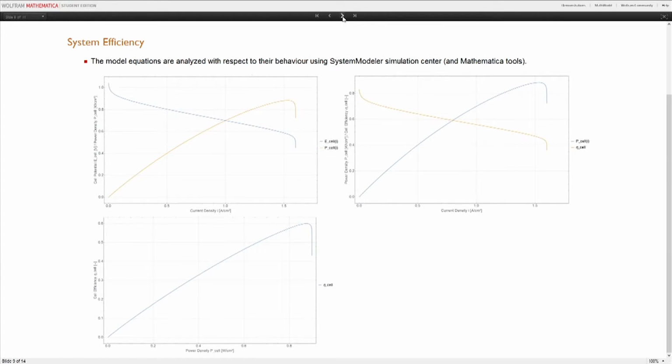And actually, this was the point for starting to consider more than one fuel cell systems, because in practical applications at this point, you size down the fuel cell a little bit to your actual load and hybridize it with a battery or something like this, so that you do not need the fuel cell to be operated in low efficiency ranges. If your actual load demand is not that high, you simply charge the battery.